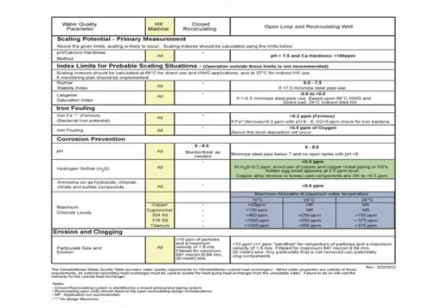The other one is chlorides. If you have any chlorides at all, under the heat exchange material column, you're going to see what we recommend based upon a couple of things: the amount of chloride, as well as the temperature range you're going to be operating in. And don't forget, for a lot of you, you're going to hook up the hot water generator, that small heat exchanger that provides free hot water to the water heater.